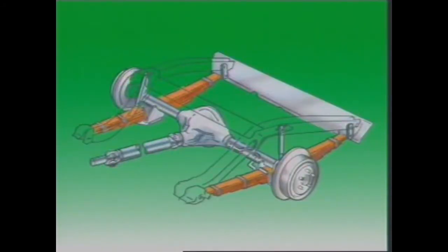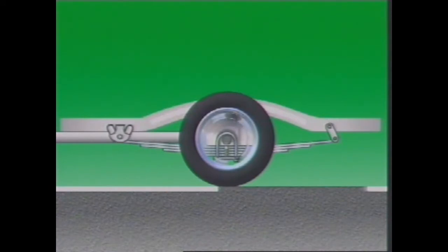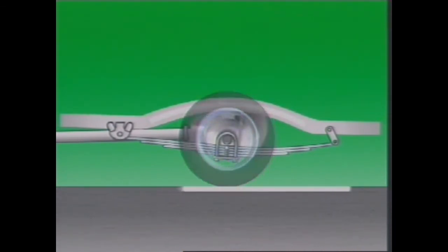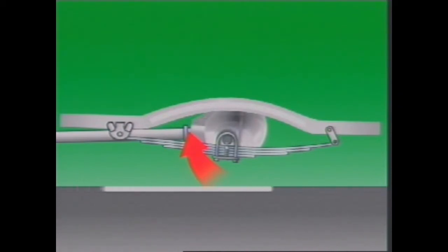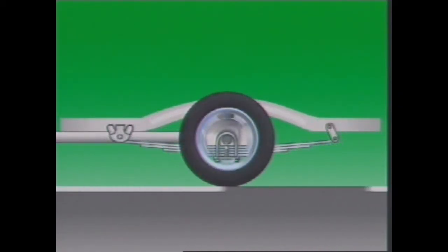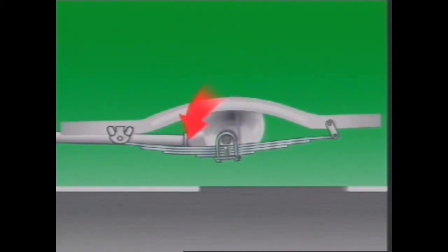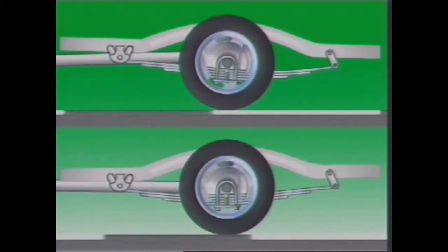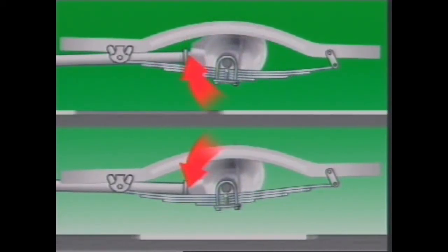The drive is transmitted through the final drive unit and axles to the wheels, and therefore the axle is referred to as a live axle. When a vehicle accelerates from rest, the resistance of its mass causes a torque reaction, producing a tendency for the axle housing to rotate in the direction that is opposite to wheel rotation. A similar effect occurs during braking, but with the twisting effect in the direction of wheel rotation. In both cases, this tendency can cause leaf spring wind-up, and the twisting action can interfere with suspension motion.